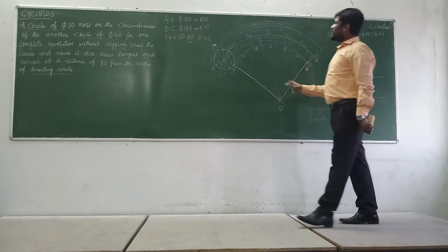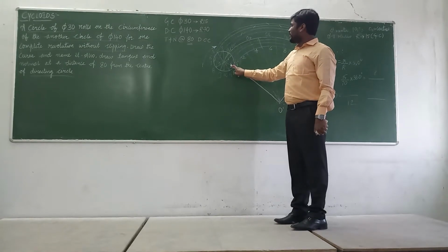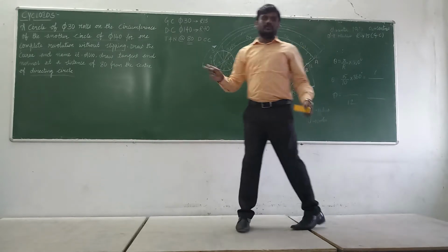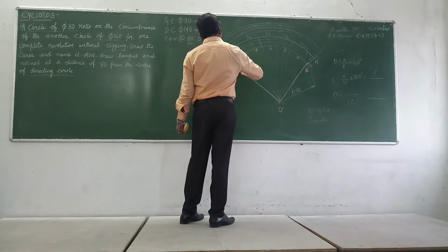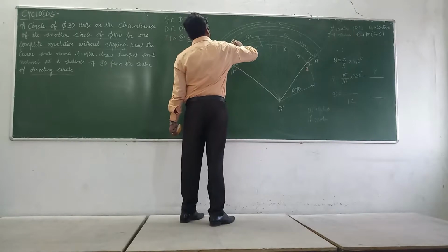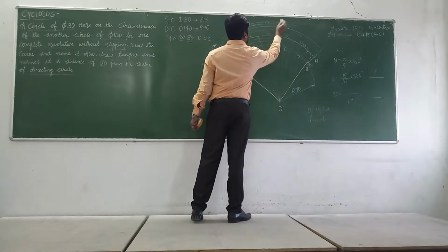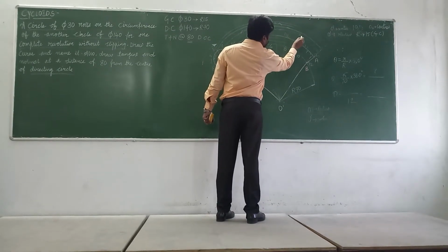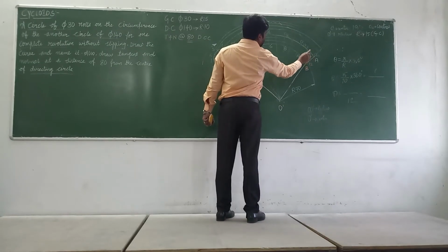This is how you get till 12; you are going to cut all the marks. So those respective dots or the arcs on these curves are the points with respect to P1, P2, this is P4, P6, and so on. So these points we are going to join with a smooth curve from the initial position P. First we trace the dots from all this. Instead of drawing directly, when you locate dots and join all these dots, you will be getting a smooth curve.